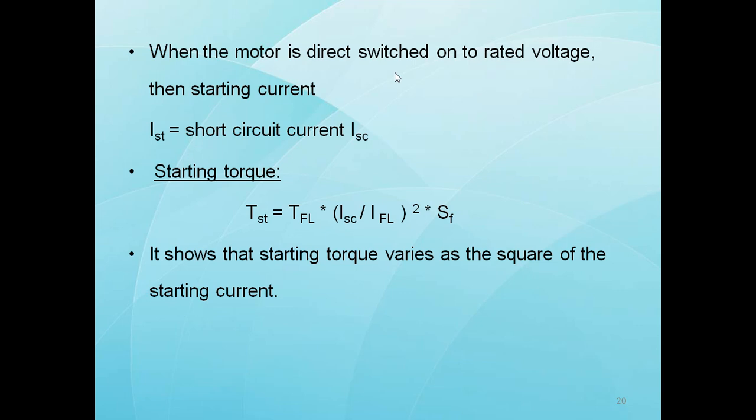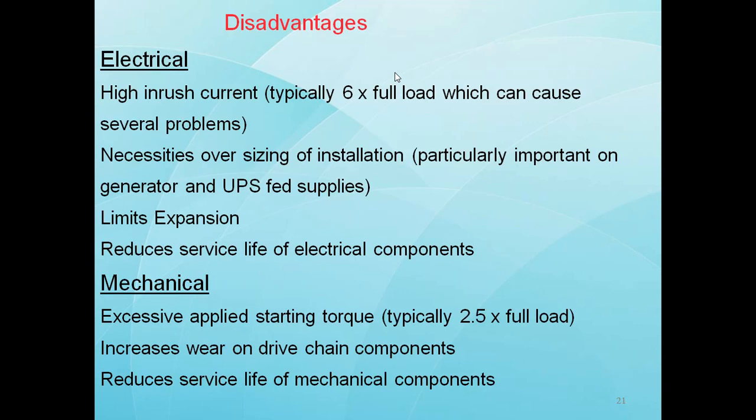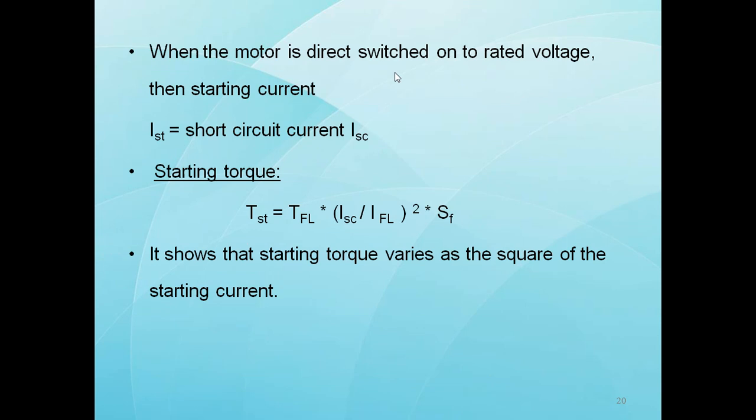It shows that starting torque varies as the square of the starting current. So from this we can say starting torque is proportional to the square of the current.